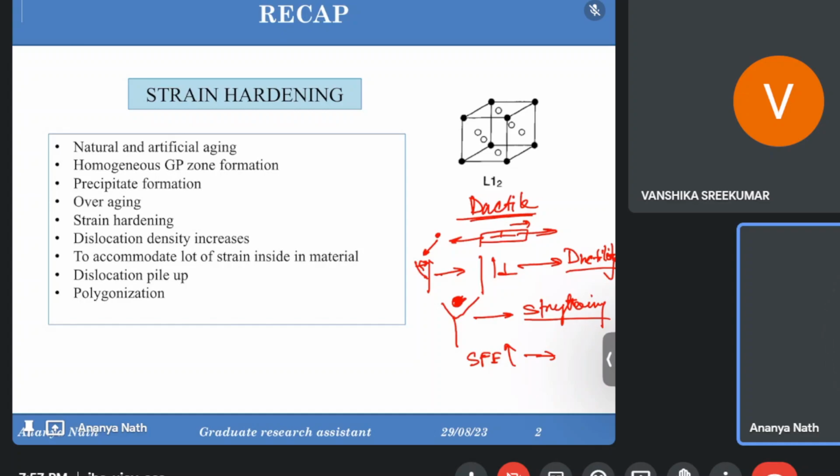But non-heat treatable alloys are challenging because they need cold working. We really cannot play with the solute atoms or alloying elements. We basically mix the alloying element to get the hardness. We are getting some hardness because of the solute atoms present inside the non-heat treatable alloys, but we cannot play further with those solute atoms to increase the hardness without mixing more solutes.